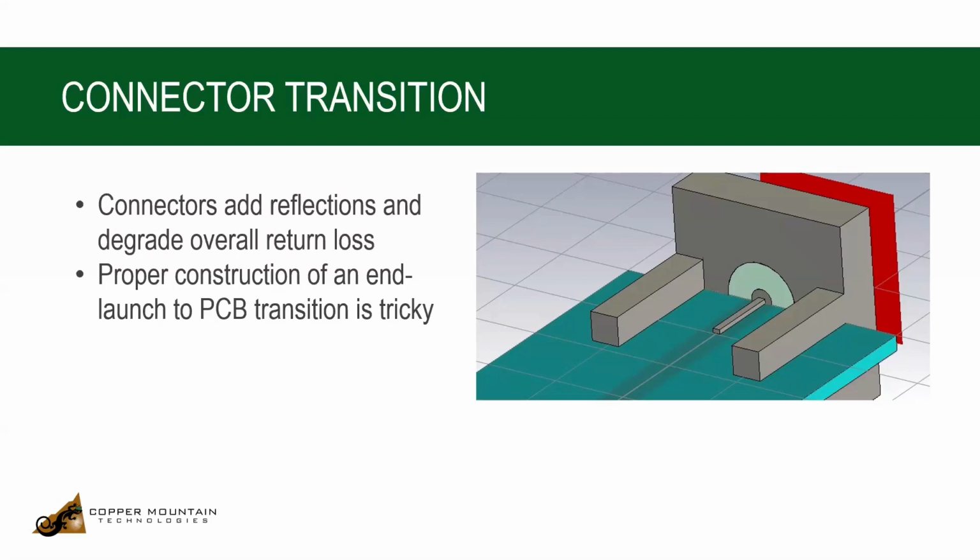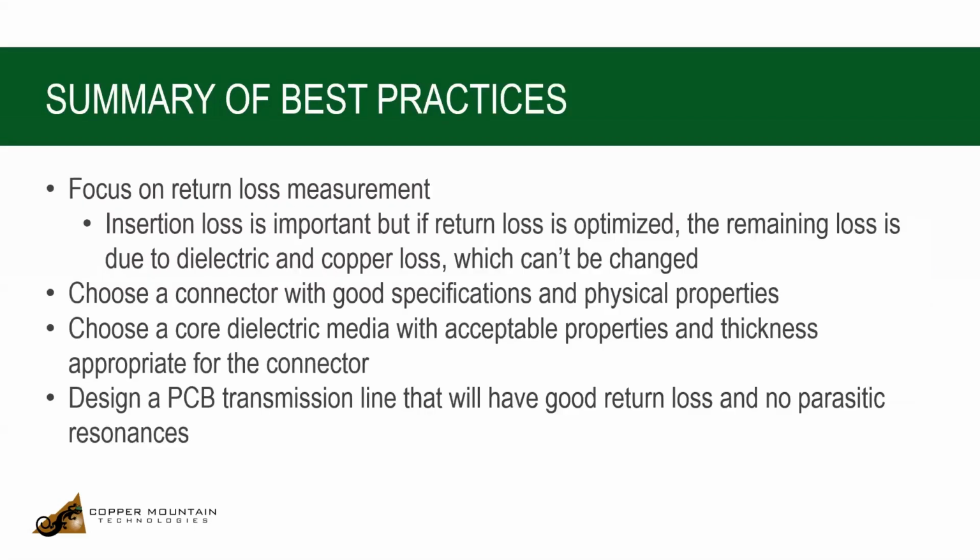How do you launch from the SMA to the PC board? Well, let's focus on the return loss measurement. Insertion loss is important, but if the return loss is optimized, remaining losses are due to dielectric and copper loss, and that really can't be changed.